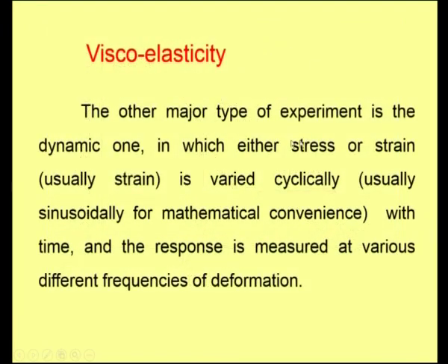The other major mode of experiment is the dynamic mode, in which either stress or strain is varied cyclically, that is, the material is subjected to cyclic stress or cyclic strain, in a repeated mode. Normally a sinusoidal waveform is used, only for mathematical convenience, and the response with respect to time is plotted for different frequencies of this sinusoidal wave.